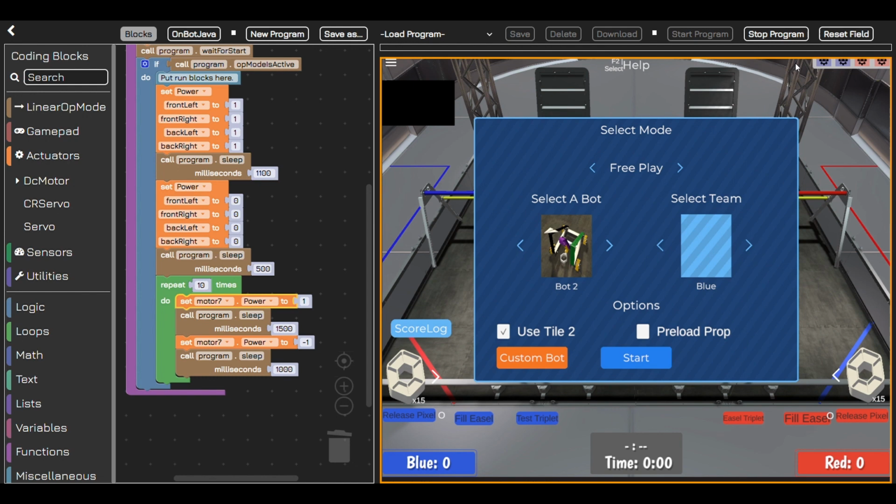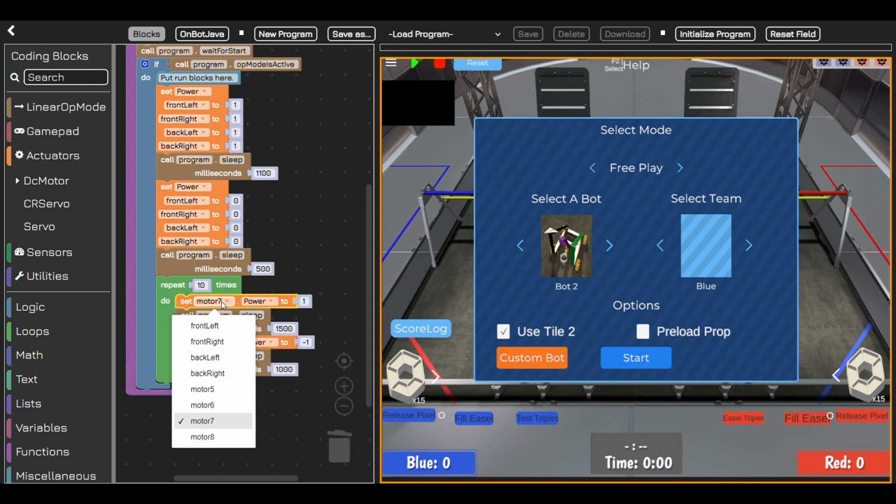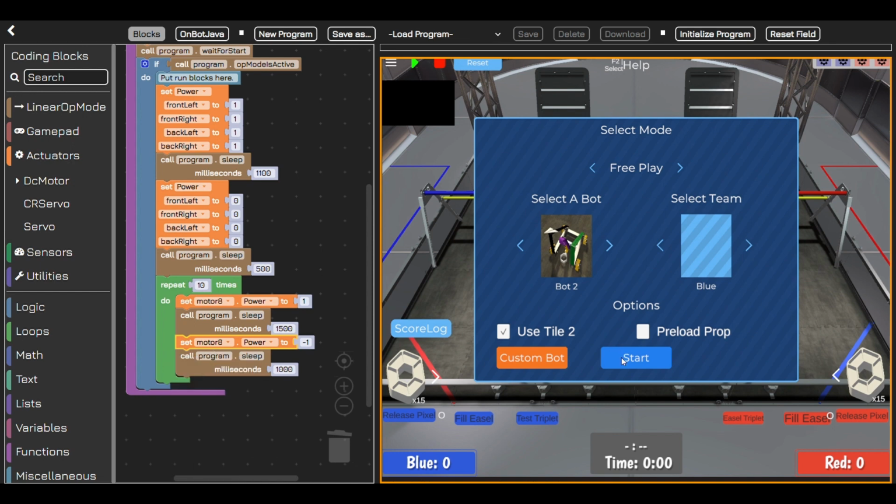This motor enables the robot to pick up and fling the airplane over controlled distances. After launching the airplane with Motor 7, Motor 8 is used to adjust the angle of the plane in flight. First, the motor power is set to 0.5 to tilt the arm pixel holder down slightly. Next, the adjust time parameter controls how long this downward tilt occurs. A longer duration results in a greater change in angle.